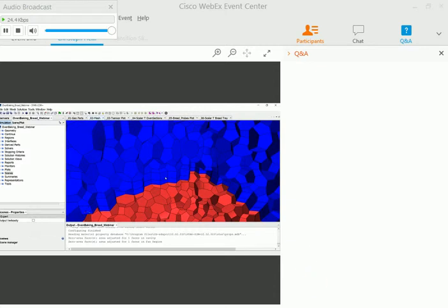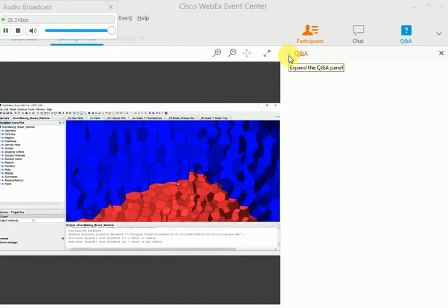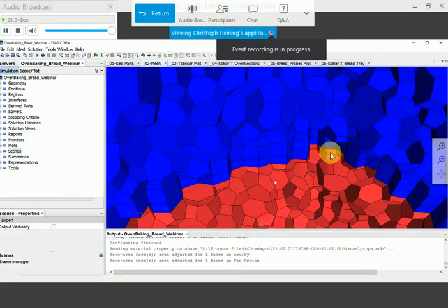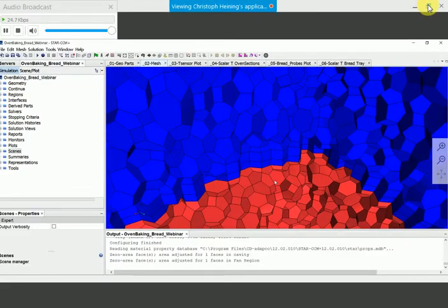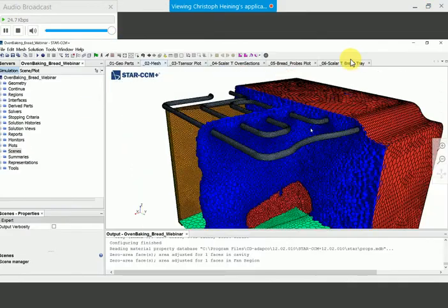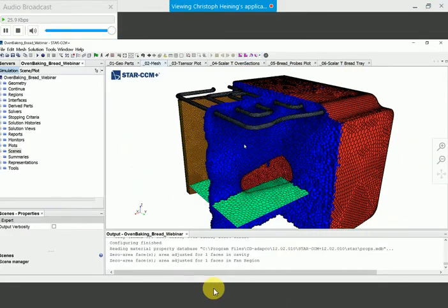Or the thermal boundary layer. And because of this, you don't lose any information when you need to interpolate your data, when you don't have a conformal mesh. So you have lots of possibilities to adjust your mesh. You define a global cell size, but at the same time you can customize your cell sizes and also the growth rates for different surfaces, for the edges, for volumetric areas, and a lot more.